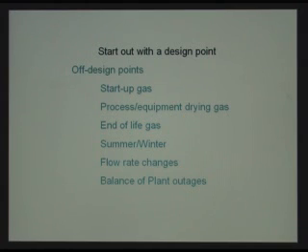Well, that means that for the first maybe several seconds, maybe several minutes, the compressor will be compressing nitrogen instead of a hydrocarbon gas. The performance of nitrogen is completely different, and so the compressor will operate in a completely different manner than you would normally expect. So by identifying the startup gas up front, we can make sure that the compressor is either sized adequately for operation on a startup gas, or that we know what performance limitations to impose during startup so that we don't exceed the operational characteristics of the machine.